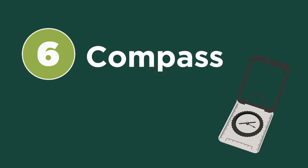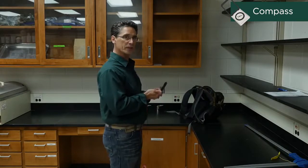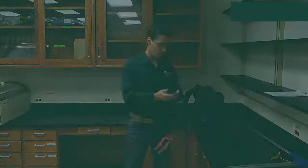Another important tool is the compass. Many of you know that compasses have a magnetic needle which points towards the magnetic north pole of the Earth. As I turn around, the needle is always pointing to the north, and I can use the dial in the compass to determine what direction I'm facing or determine what direction I want to go in. In forestry, we basically use the compass to navigate around the forest and also to mark the angle as well as the distance with the measuring tape between objects in the forest.